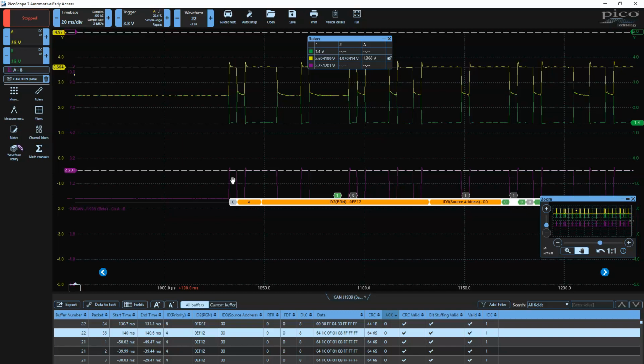The threshold for this to be considered a dominant bit is pretty much guaranteed: if it's above 1 volt, it should be guaranteed within some limit to be considered a dominant bit. If it's below some threshold, I don't remember what that is, then it's guaranteed to be a recessive bit. So in this case, our recessive bits are really good. We've got a difference in voltage here of near 0. As I indicated, this is a pretty healthy network.